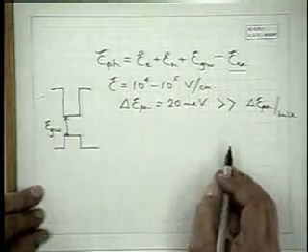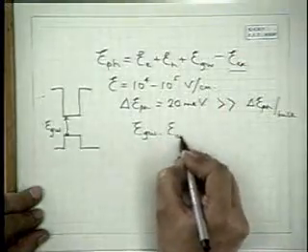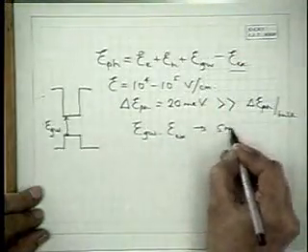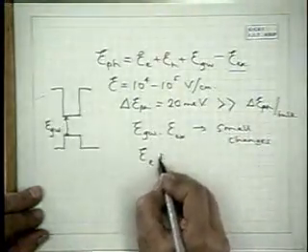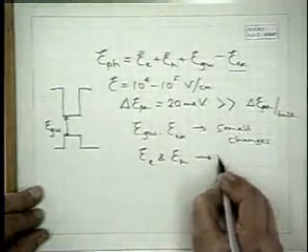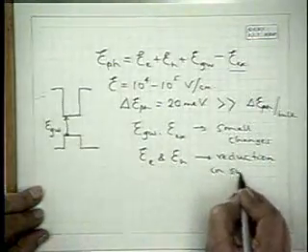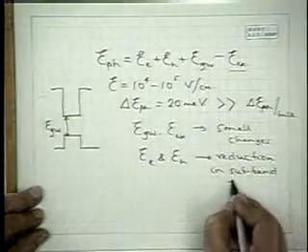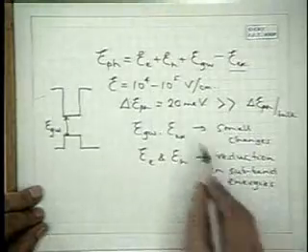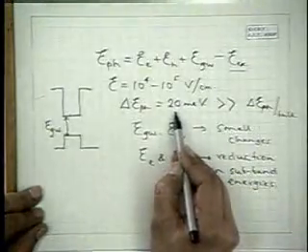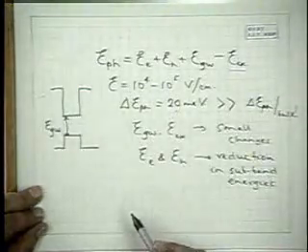So with an electric field, EGW and EX have small changes, but EE and EH, there is reduction in the subband energies. So this accounts for the rather large change, 20 meV, whereas we've seen that in the bulk this is of the order of a few meV.